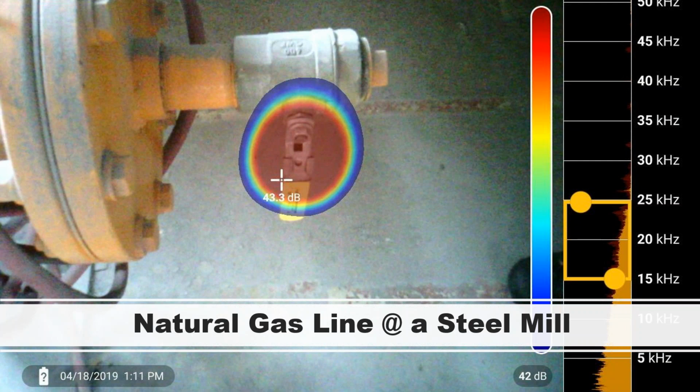They recognized right away. I thought it was a big compressed air leak. We went and looked at it, because we don't have any compressed air lines there. That's a natural gas line. We got up on the mezzanine, looked a little bit closer. They actually got a sniffer out too and looked at it. And sure enough, it was up there accumulating methane up on the top of the building, which could have been catastrophic. So that was a good find that day.